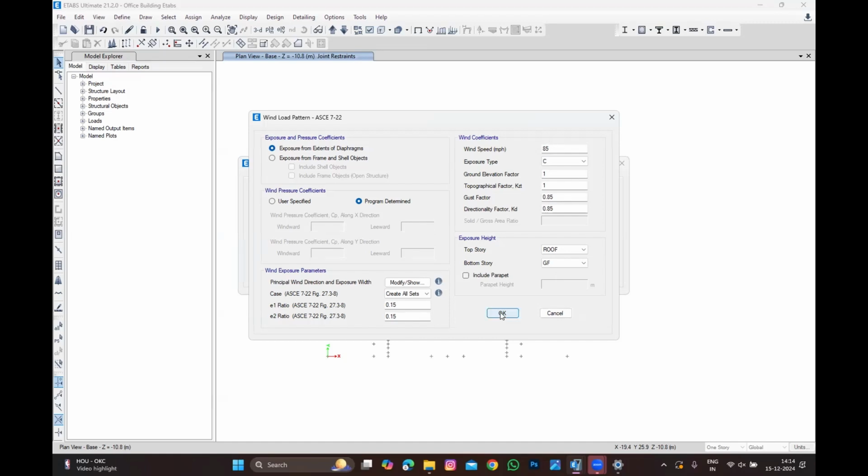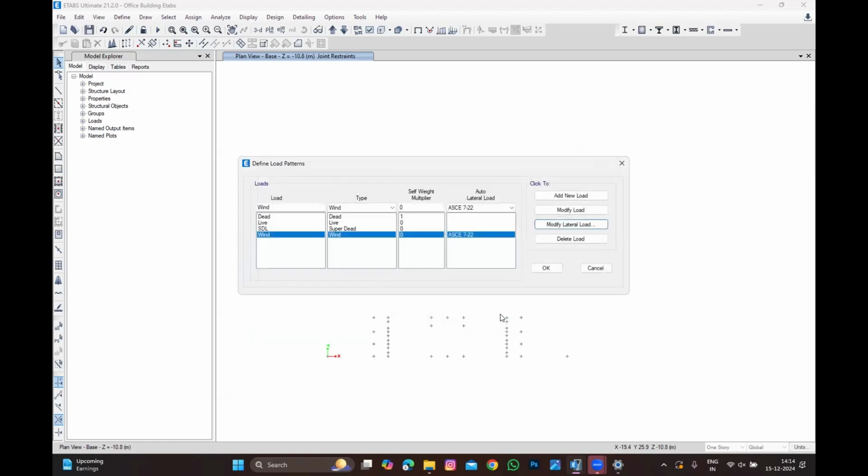It's up to us, sir. Even the authority will never force you. Up to 1.2, it is okay for them, they will never even ask you. But if it is more than 1.2, mostly they will go for concrete work, 100 mm, 125, 150 mm wall.